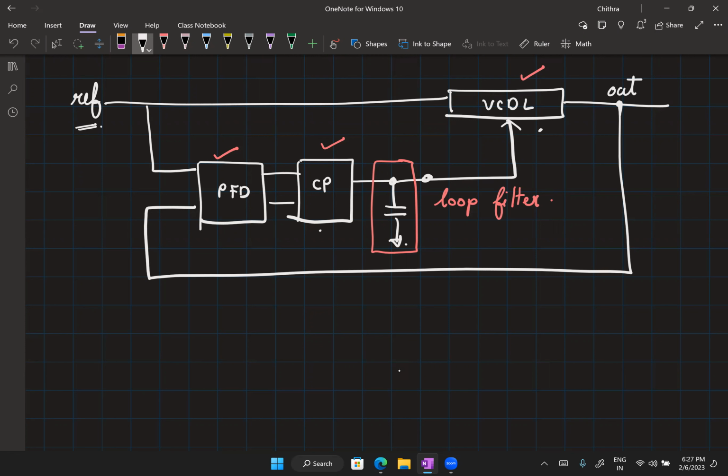But there are circuits where you turn off the feedback for some time. Then the circuit is in open loop. But then you have to periodically switch on the negative feedback so that it comes to the correct point, and then you can turn it off again. So there are certain negative feedback systems where the feedback is not continuously active. But for now, we will assume that the feedback is continuously active. And on top of it, I'm asking the question, does this circuit also exhibit any discrete time behavior?